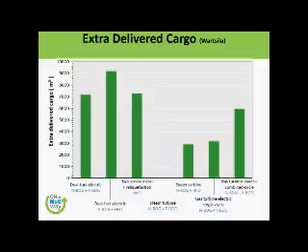And this is dual fuel electric, which is using natural boil-off or forced boil-off. This is what they have got: dual fuel electric, also natural boil-off, and a two-stroke diesel engine plus reliquefaction plant for HFO. Natural boil-off steam turbine is getting lower and lower, as you can see. So this is just giving you an idea of how the industry is using the gas.